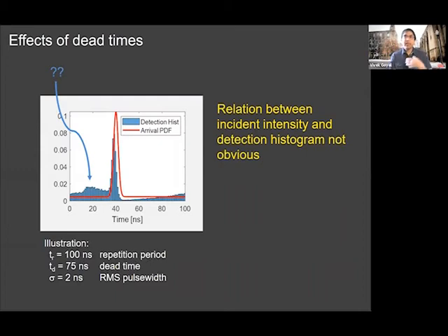There may be some fog between you and the object that's at 40 nanoseconds, since the secondary peak is quite broad. Or maybe the breadth of this secondary peak actually suggests that it's an aliased component coming from around 120 nanoseconds, but aliased back to around 20 nanoseconds.